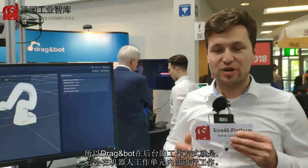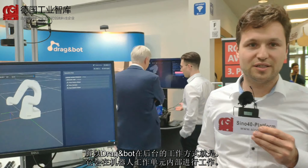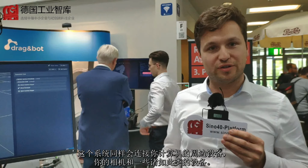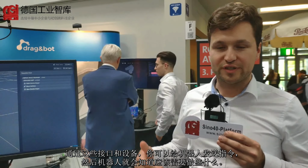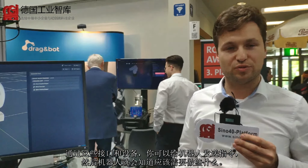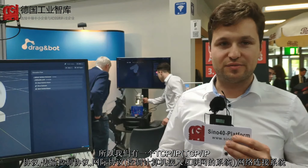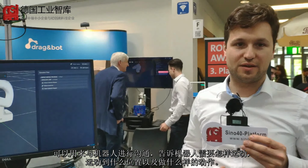So the way Drag&bot works in the background is there's an industrial PC that's located within the robot cell. This industrial PC has the application logic, what has to be done first or the other. Towards this PC, all your peripherals are connected, so your grippers, your cameras, and things like that. Over this interface and this industrial PC, we send out the commands to the robot so it knows what to do. When we integrate a new robot, we write a driver. So we have a TCP/IP Ethernet connection that we can use to communicate with the robot and tell the robot what to do and to what extent and what position.